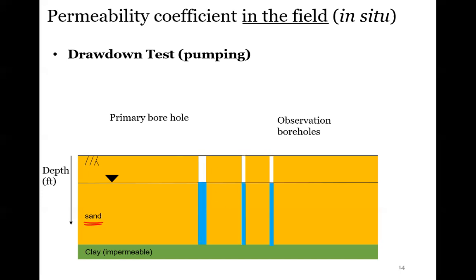And I should say, these aren't just open boreholes. These would be filled with casing, and the casing will have holes drilled into it to allow water to flow through. Then we'll apply a mesh around the outside of it so it allows water to go through, but not soil to fall in and plug those holes. So that's what these boreholes actually look like.